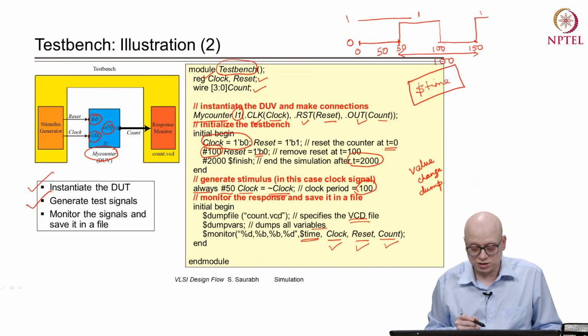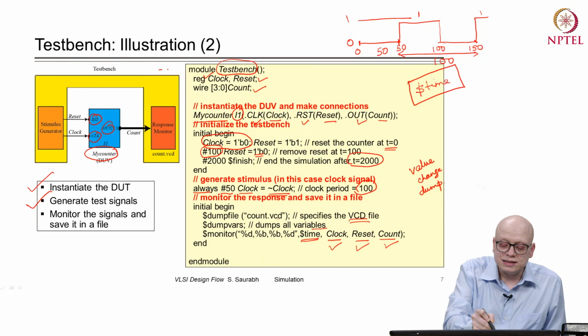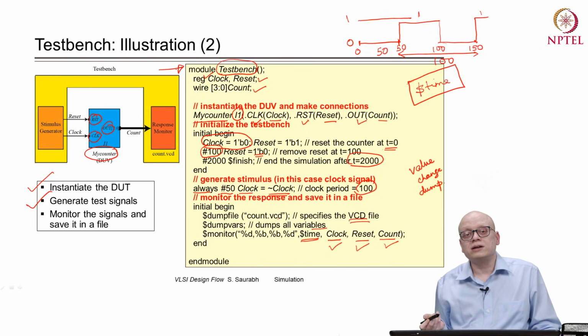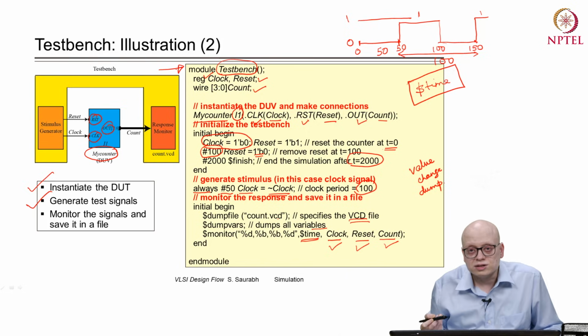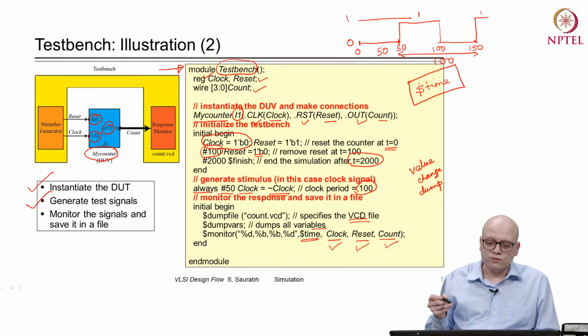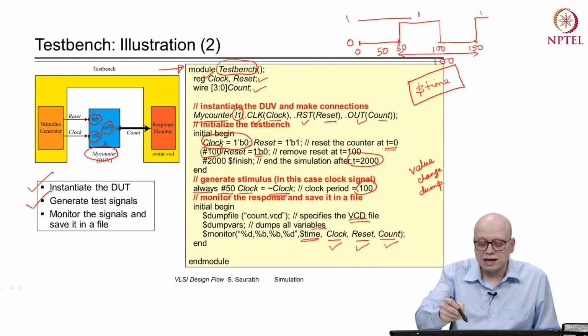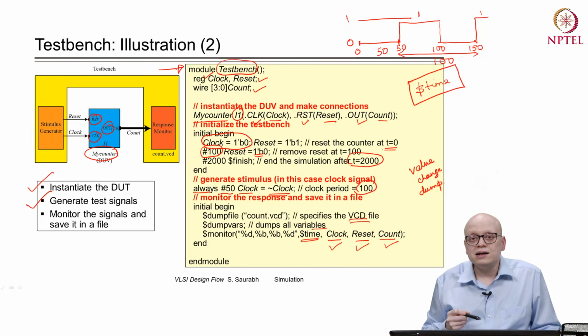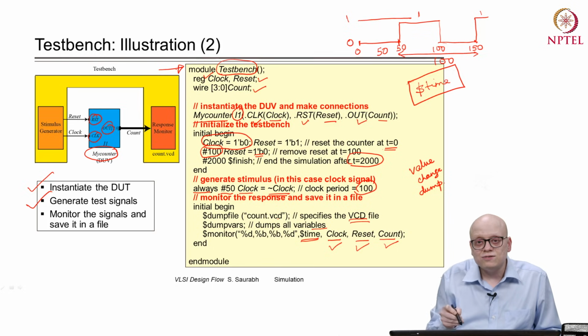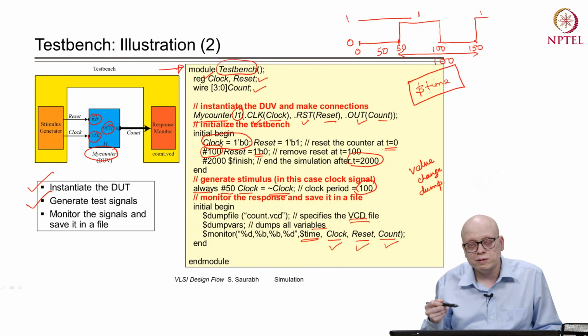Now, we can run this test bench in the simulator, right. There are some commercial simulators, and there are also freely available simulators for Verilog. In those simulators we can load the design and load this test bench and ask the simulator to simulate, and once it simulates, the VCD file will be created and all these signals will be monitored.